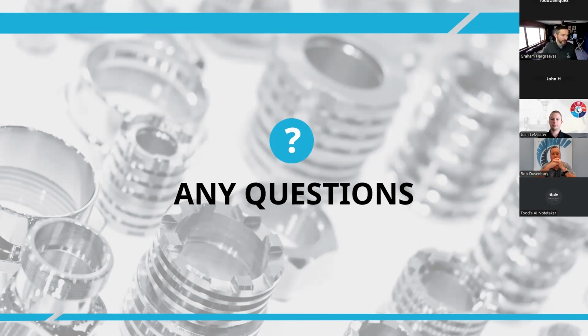So this is not to support true 5-axis toolpaths, not at this point. Not simultaneous 5 right now. That's the goal down the road. Simultaneous 5 is a tougher nut to crack, unfortunately. For the time being, it's 3-axis and 3+2. And in the future, we'll be supporting 2-axis turning, multi-axis. That's a ways off yet, though. So just those two for now.